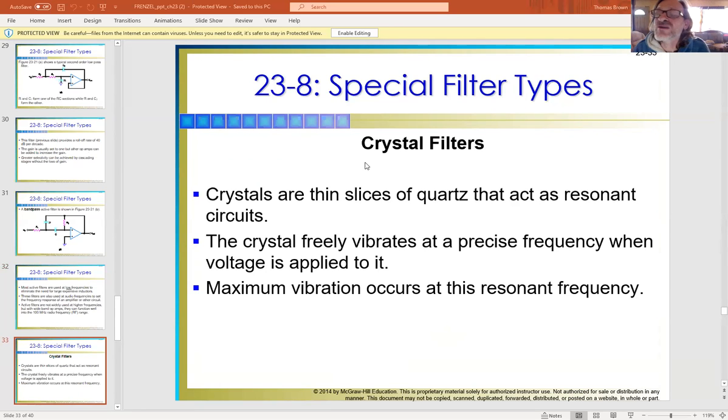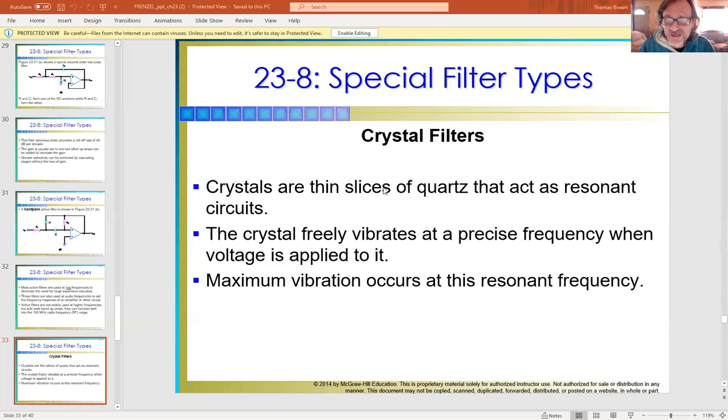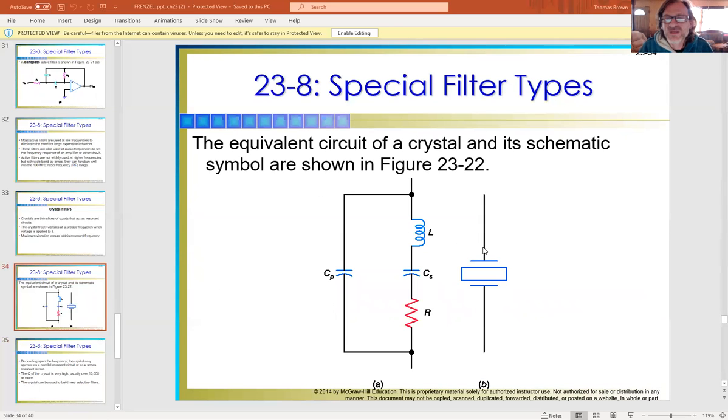If you buy these things off the shelf, let's say you wanted a 1 gigahertz frequency, you would buy the 1 gigahertz crystal and it would provide you that clock consistently. You don't have to do any other parts. We wouldn't have to set up an RC circuit with a specific frequency in mind and have to deal with any inequities with the parts. These crystals will only set at that particular frequency.